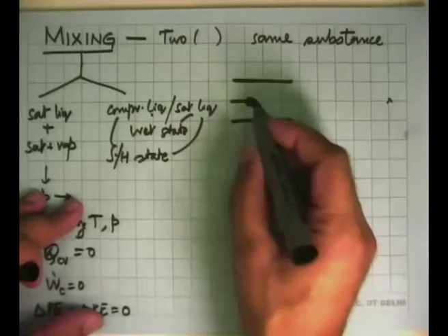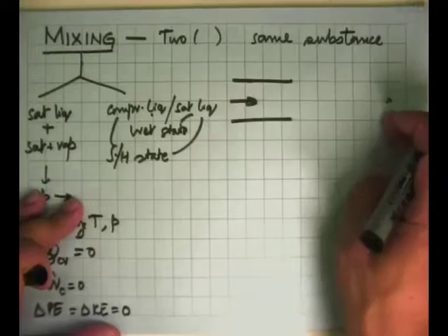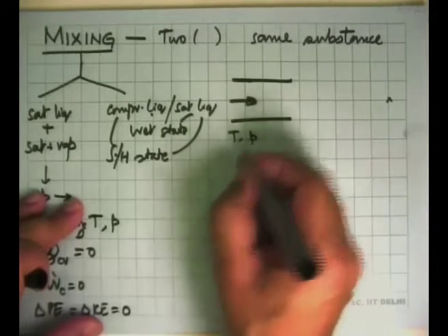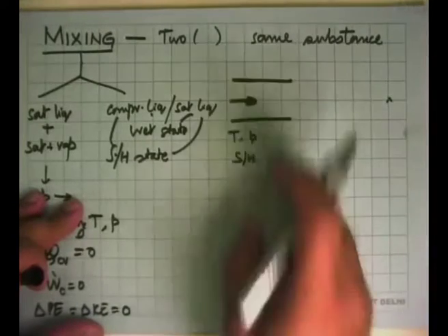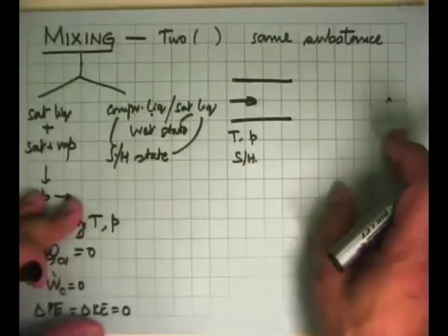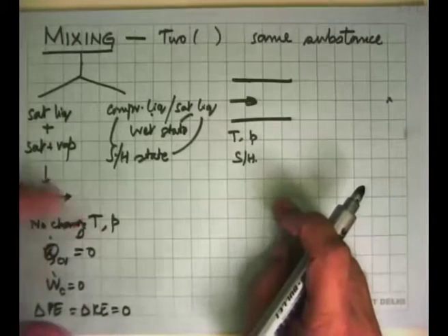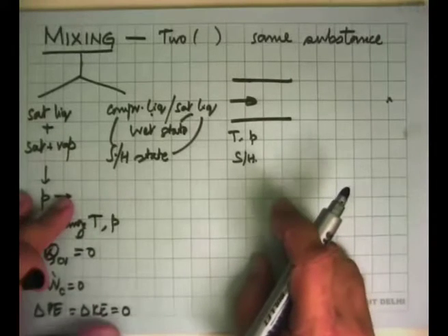But what if I want to reduce the temperature of this? Then theory will tell you that if you have steam at a certain temperature and pressure and if it is superheated or saturated and you want to reduce the temperature, either you expand it in a turbine or you expand it in a nozzle, both of which are not practical in most cases.